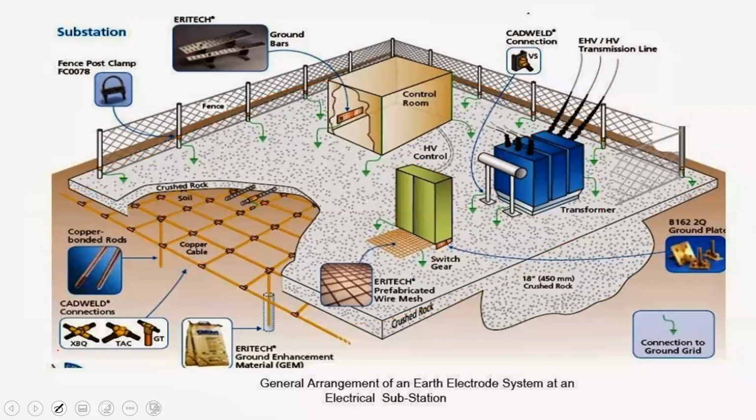Ready? One, in terms of depth. The deeper you bury it, you can help to reduce the overall resistance. Two, the number of meshes. Each of these is a mesh within your grid. So you can increase the number of copper meshes. If you make more meshes, that's two.